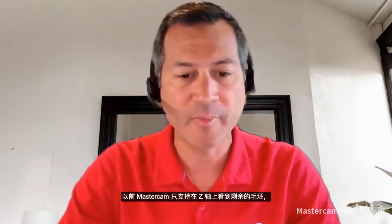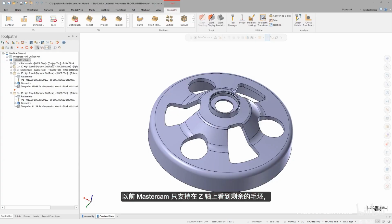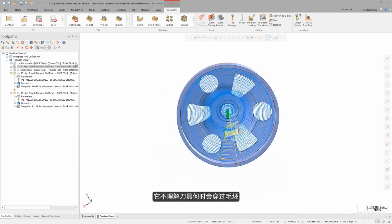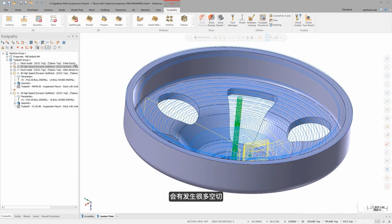Detecting undercut stock in Mastercam 2023 has been a long time coming. We understand the need, we've understood the need, and we finally have been able to implement it into Mastercam 2023 without our customers feeling it, as in processing time taking significantly longer. So in the past, Mastercam only saw the remaining stock basically down the Z-axis. It did not understand when the tool broke through the stock. It would continue to machine and cut air.